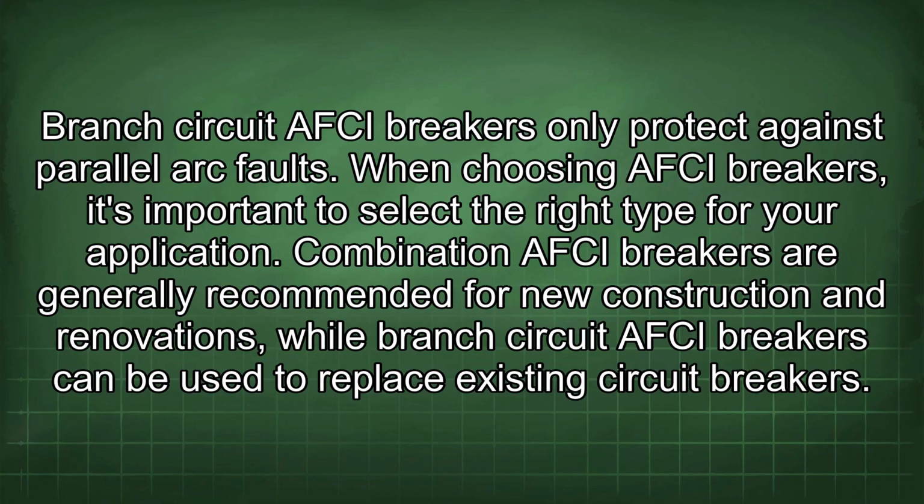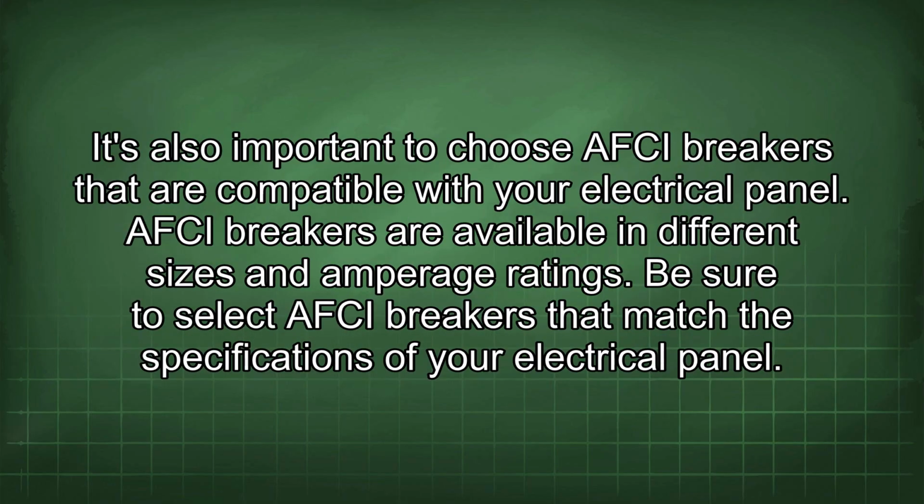When choosing AFCI breakers, it's important to select the right type for your application. Combination AFCI breakers are generally recommended for new construction and renovations, while branch circuit AFCI breakers can be used to replace existing circuit breakers. It's also important to choose AFCI breakers that are compatible with your electrical panel. AFCI breakers are available in different sizes and amperage ratings. Be sure to select AFCI breakers that match the specifications of your electrical panel.